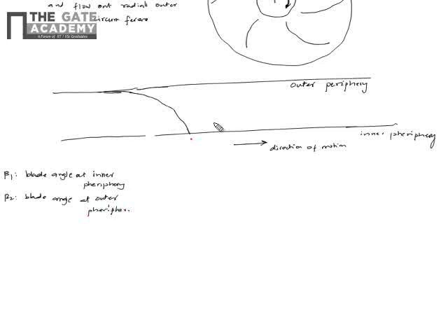As it is rotating like this, this is how the fluid enters. Relative to the blade, the fluid will always enter tangentially. If you imagine sitting on the blade at this point, the flow is just tangential to the blade as observed by an observer on the blade.